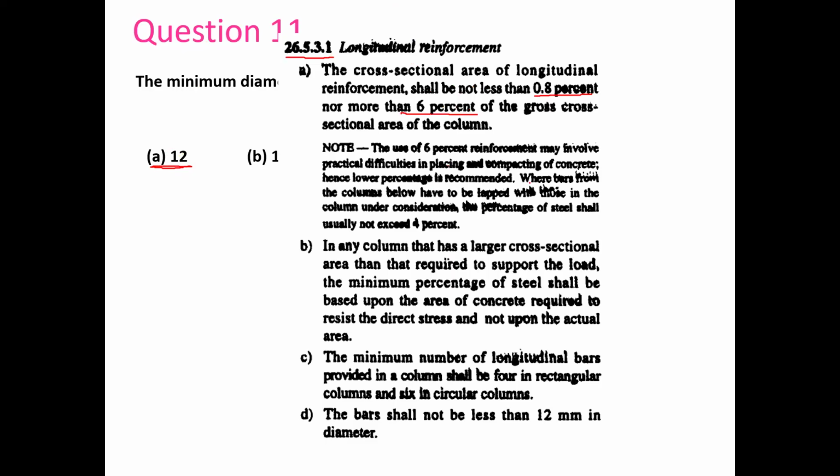Preferably, as they have mentioned over here, it has to be 4%, not exceeding. So we can go 4%. In critical cases you can go over 4%, but preferred is 4% or less than this. Then here, the bar shall not be less than 12 mm in diameter.